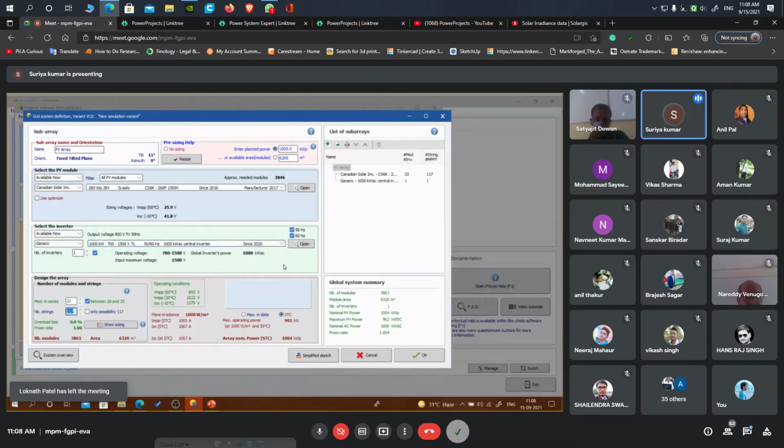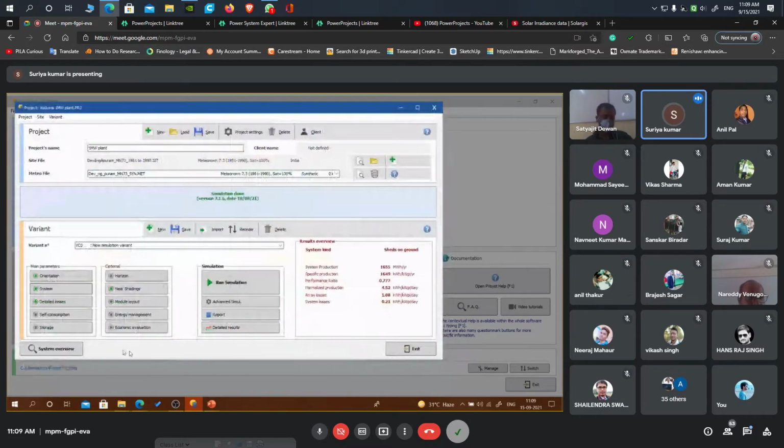Now here, for example, I will say this is 1000 kilowatt peak. Kilowatt peak is going to be the DC capacity and 1000 is going to be the AC capacity. Then DC by AC is going to be 1, right? If I am going to have 850 kilowatt as AC output, then it is going to be like 1.2 or 1.3, depends, right? I can go up to 1.3 to avoid overload losses. If I am going above, then it will have losses.